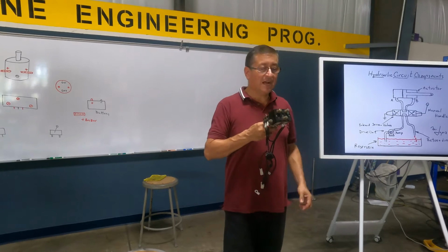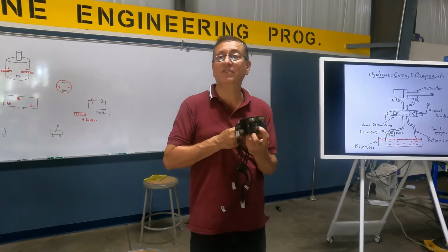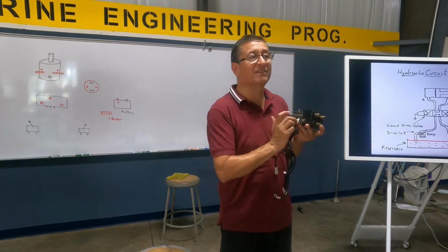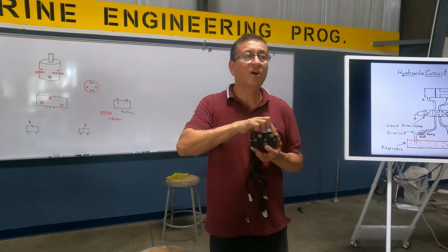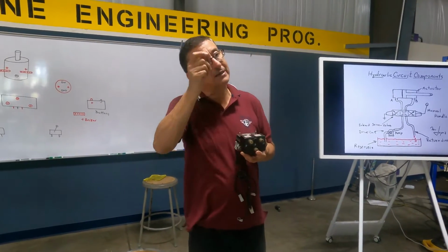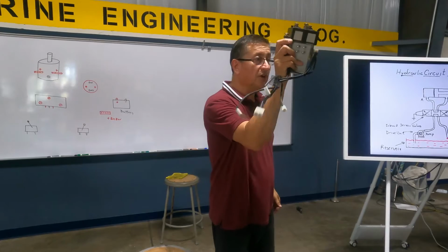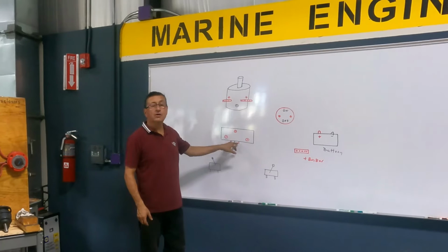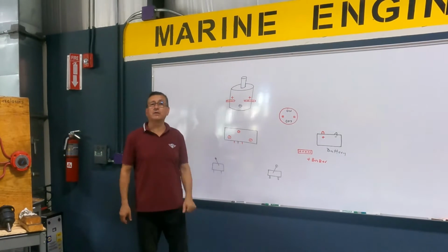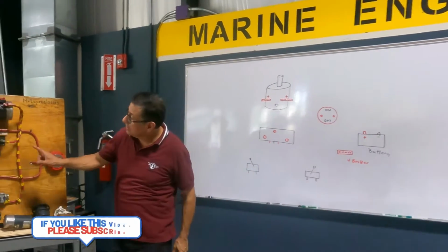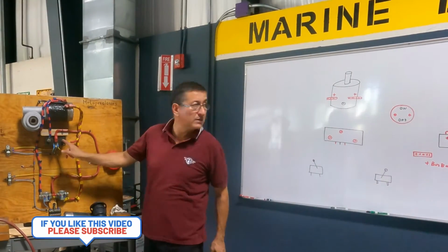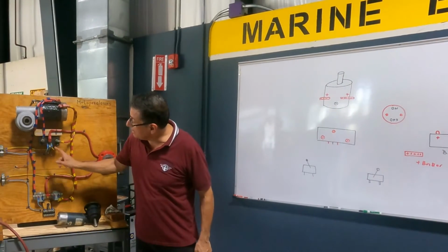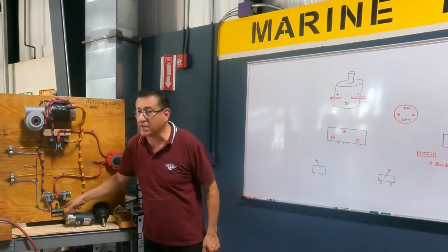It's very common. Look, the power enters here, the big positive enters here, and depending on the position of the signal, it sends the current to this side or this side, and the motor rotates like this or like this. This is the solenoid control box. I have the solenoid control box here with the signal. Positive, and negative in the middle. On the solenoid control box, look, three big positives, and the signal positive, and the negative in the middle connected to the negative bus bar.